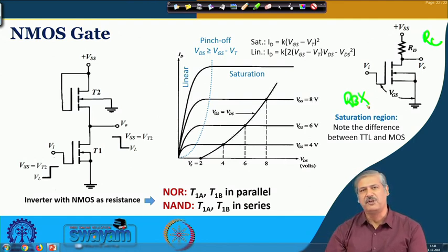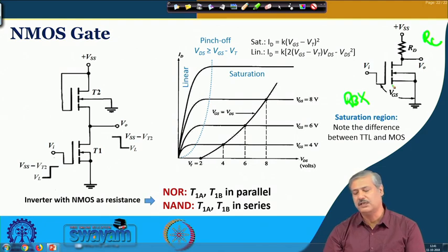Its input impedance is very high, and this is an n channel enhancement mode MOSFET that we are using here. N channel is used because electron has higher mobility. Enhancement means that when a particular voltage, called the threshold voltage, is applied, an N channel is formed, and as long as the voltage remains more than that, the channel is there and the current flows.